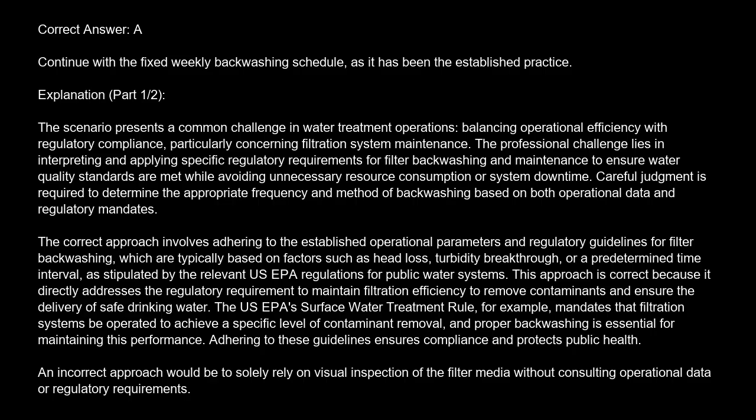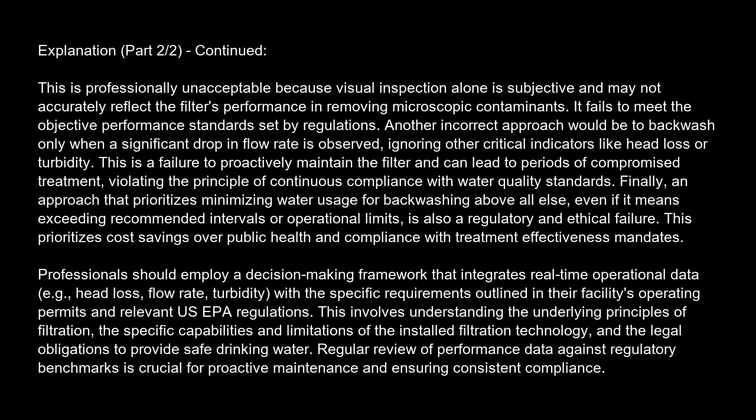Adhering to these guidelines ensures compliance and protects public health. An incorrect approach would be to solely rely on visual inspection of the filter media without consulting operational data or regulatory requirements. This is professionally unacceptable because visual inspection alone is subjective and may not accurately reflect the filter's performance in removing microscopic contaminants. It fails to meet the objective performance standards set by regulations.